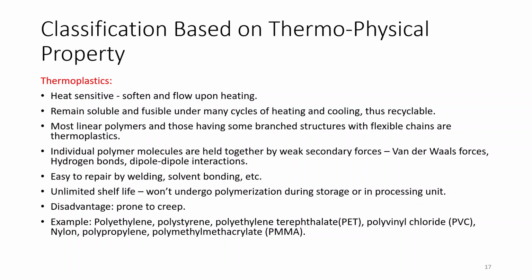Most linear polymers and those having some branch structure with flexible chains are thermoplastics. The individual polymer molecules are held together by weak secondary forces, van der Waals forces, hydrogen bonds or dipole-dipole interaction. They are easy to repair by welding and solvent bonding. They have unlimited shelf life and won't undergo polymerization during storage or in the processing unit.